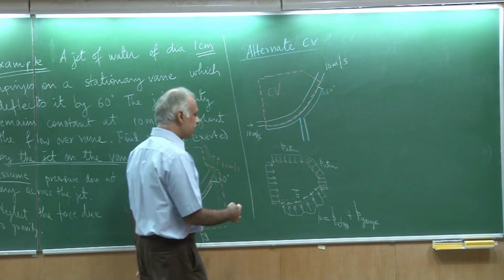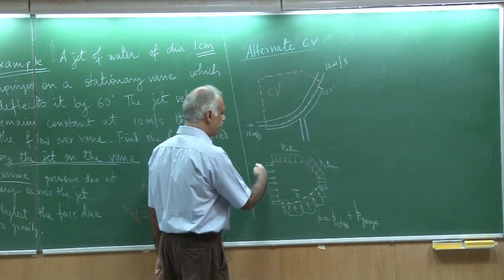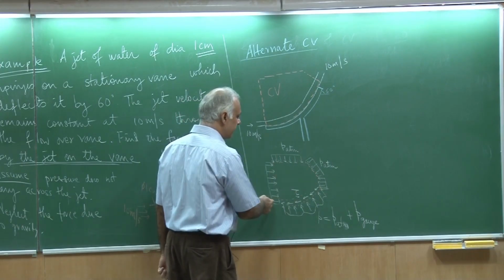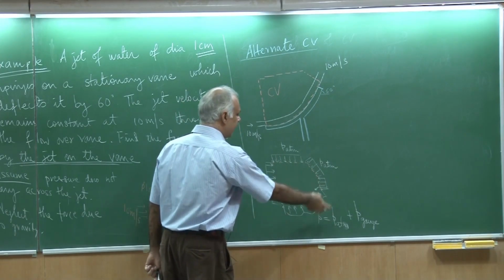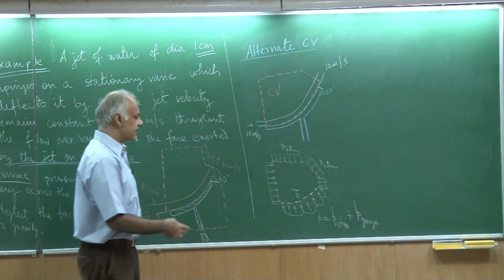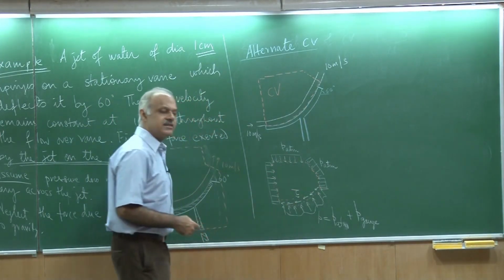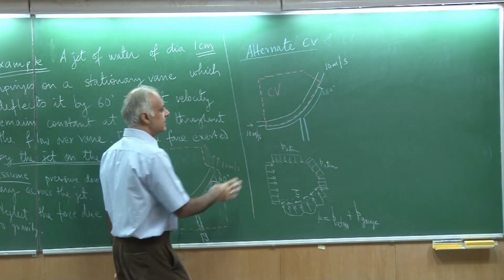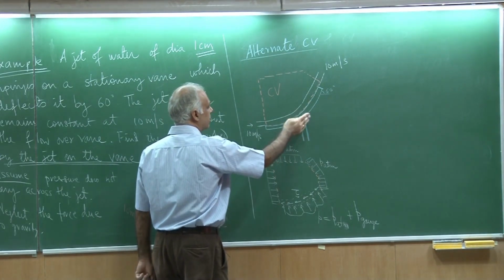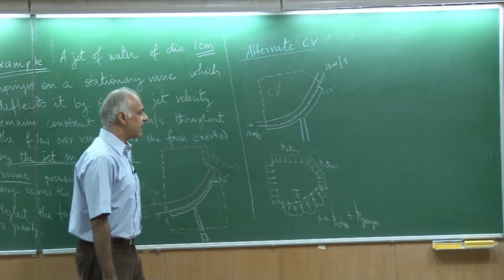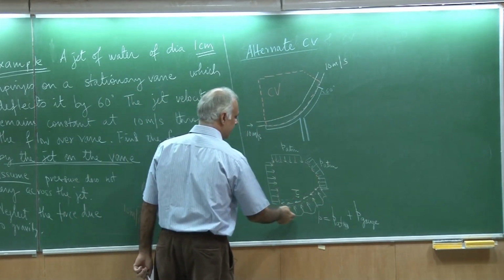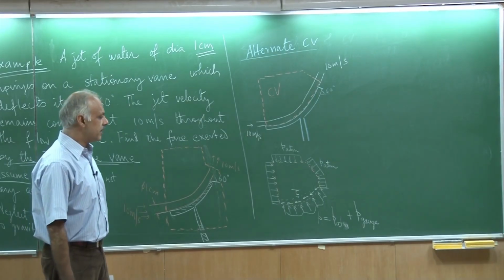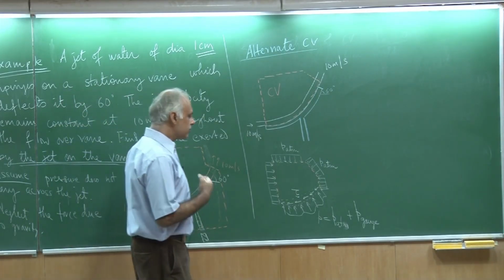So, when I apply now the Reynolds transport theorem, the force acting on this control volume is not just the atmospheric pressure, it is actually now the reaction, the total resultant coming out from this system of stress and pressure distribution. Notice, I really do not have now the force from the vane as such, because what I see is the pressure and the stress that is transmitted to the fluid from the vane. So, now I do something smart.